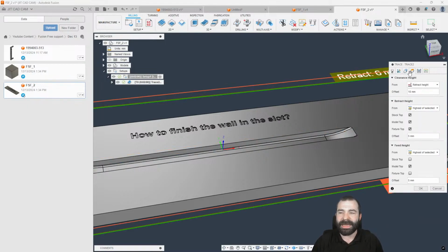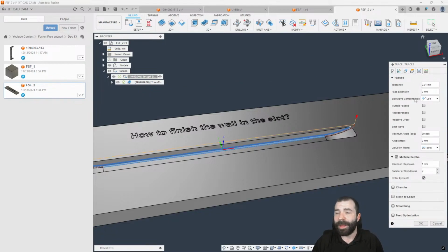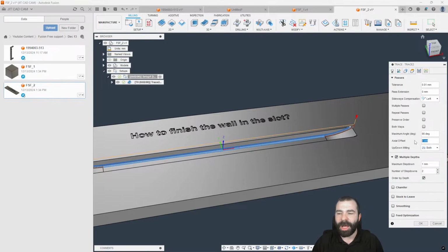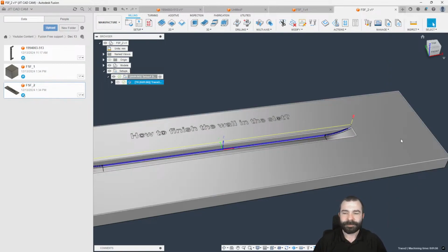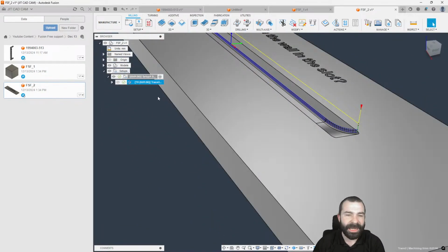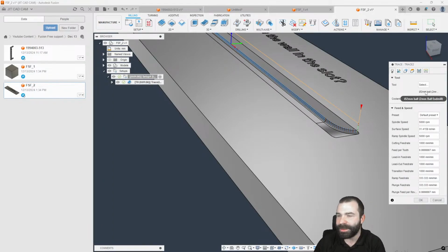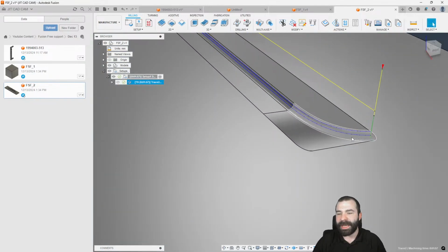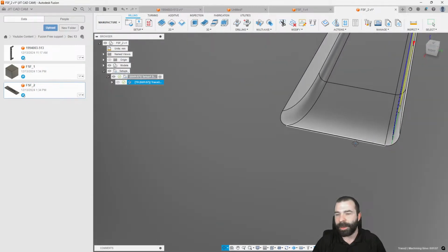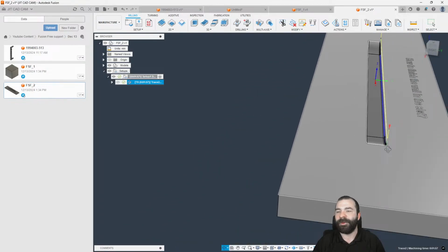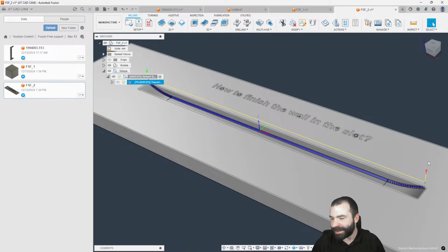But the idea is in my heights tab, or actually not my heights tab, I apologize, guys. This is where we're going to use an axial offset, right? So if I know my tool is a 2 millimeter ball, I need to offset -1 millimeter. And as you can see, we could bring that tool further down to machine in our part. And in this case, I think I actually need -2. I think my brain is working backwards because it needs to be based off -2. But as you're seeing, we can bring that tool down with the axial offset to get it pushed into our part. Again, because we are using cutter comp left as well, we need to make sure that we're compensated far enough away. So I hope that answers your question on this first one.